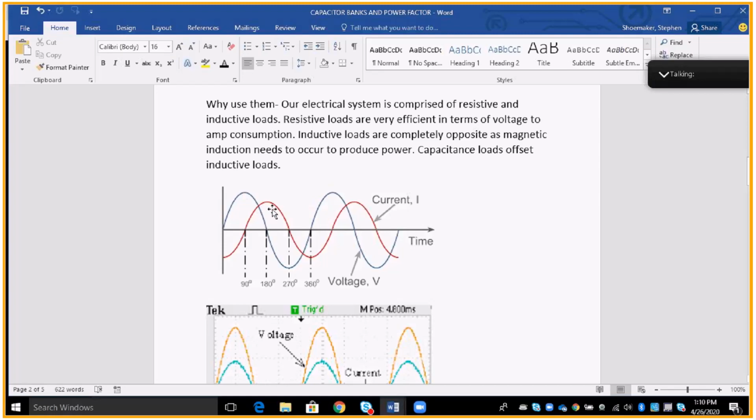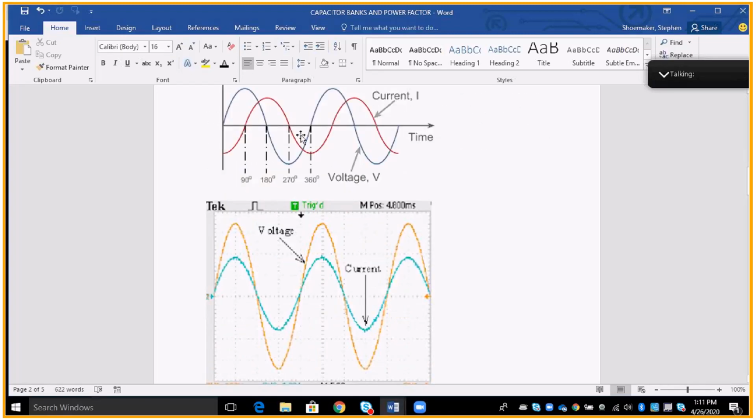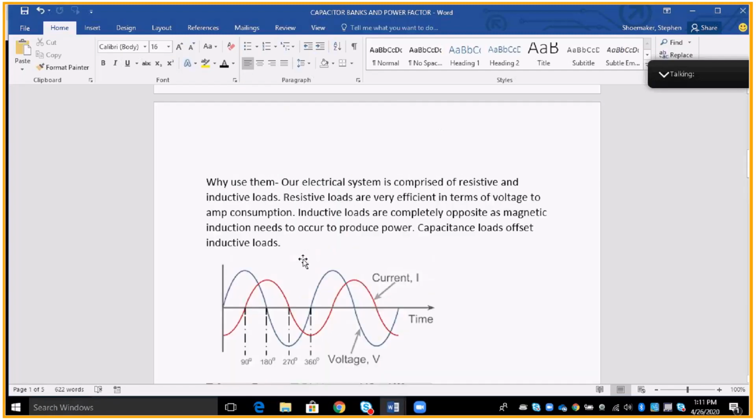That is the most undesirable way that you want your circuit. So you want capacitor banks to adjust and bring it back to its resistive form the best that it can. I just want to stress though that that's dynamic, that these lines are moving all the time. And of course there are times when the bank's going to come on and offline as needed.